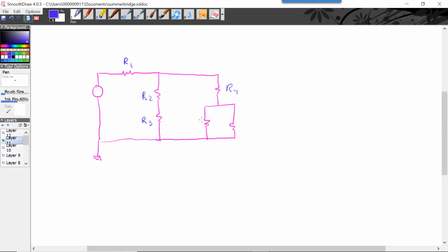And we'll label them. Now, if you're trying to identify, just looking at this circuit, what's in series and what's in parallel, well, that really means, you know, kind of the raw device. Now, some of you probably already know that R1 is in series with this equivalency, but R1 is not in series with R2 and R3 because the rest of these resistances would impact it. So the things that are in series without transformation,